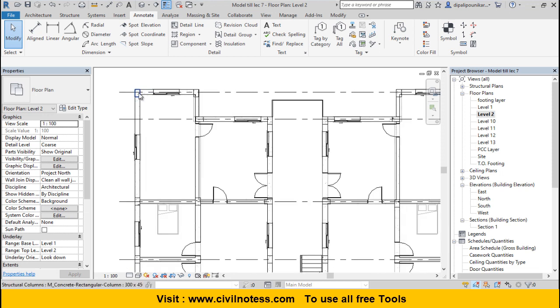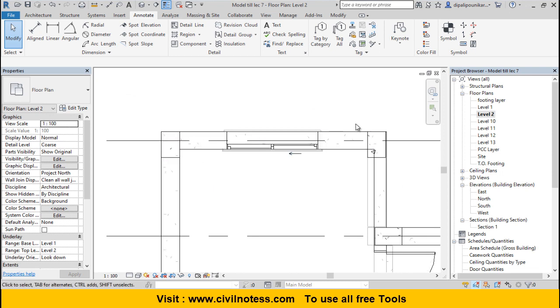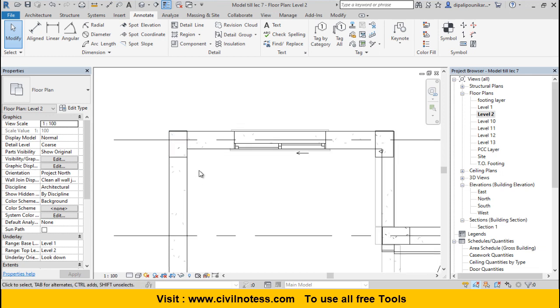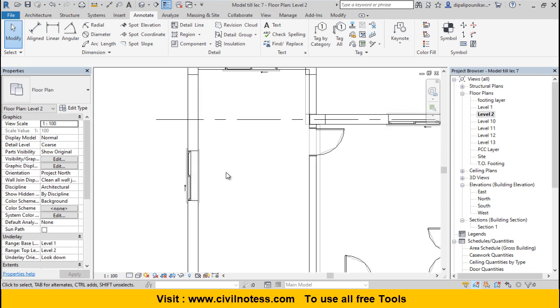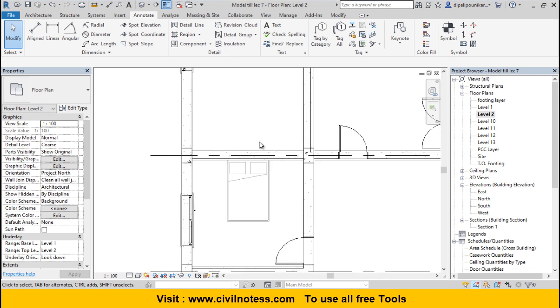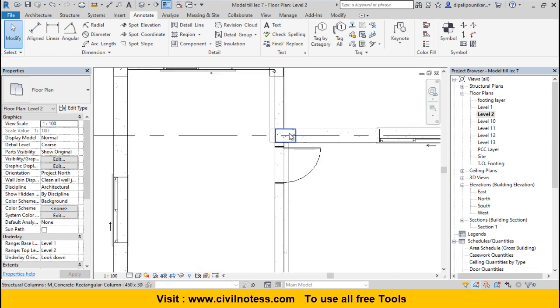You can see we require this floor plan. If I take the center to center distance, what does it mean? It means this wall also comes till this point. But here a column is already established. Is it really required to take center to center distance? No, not at all. But this concept works when there is a junction of wall. When there is a junction of wall available at that point, you can use this concept. But if you have a column up to that point, this concept is not going to work at all.